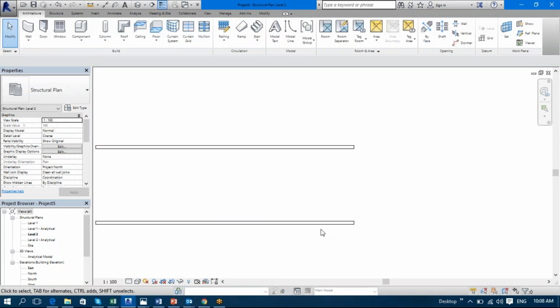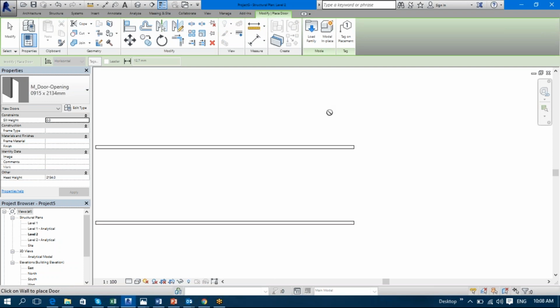One second. DR. Now, first of all, the moment I have selected DR, you have to see the first principle of Revit, the contextual tab. Then second, the options bar, and third, your edit properties. Now, please write it down. In this property palette, the first part which you are able to see is called the type selector.